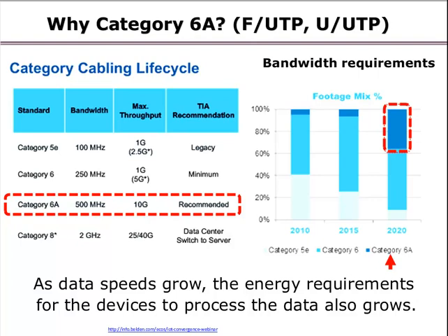With many businesses now going online, cabling with high bandwidth will be required to move data across the network. So, to transmit high electrical power and high-frequency data concurrently, a high-performance cable, such as Category 6A, is recommended. Category 6A cabling can provide the high bandwidth required and remote powering capabilities that the emerging applications require. However, it is important to understand the thermal performance of the cabling over a long period of usage.